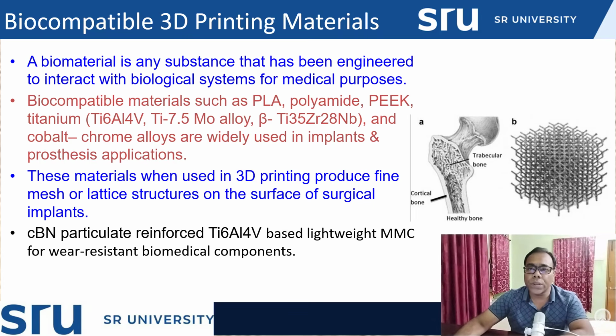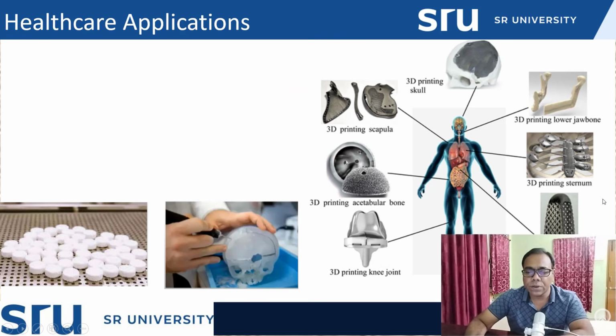So to increase the wear resistance of titanium, one can reinforce it with CBN, because CBN has high wear resistance, so it will decrease the wear of the implant. So one can use it for this application.